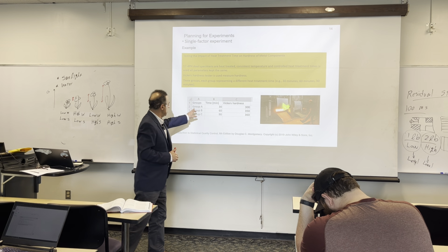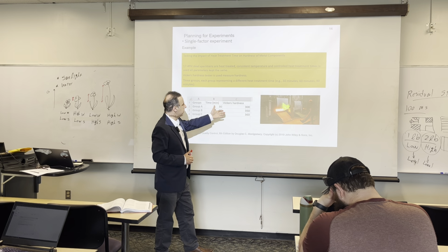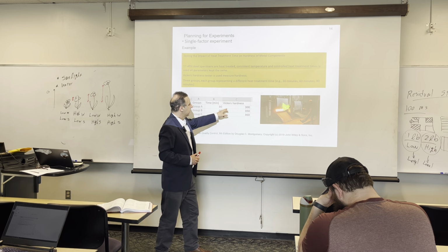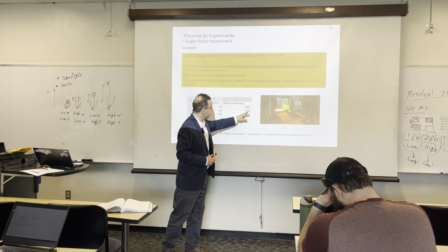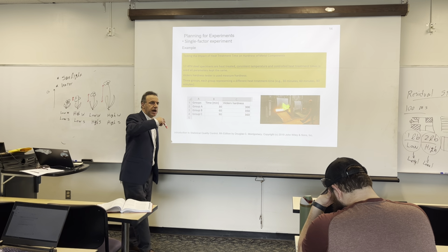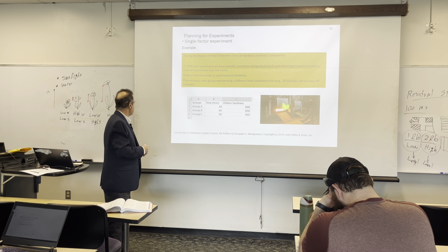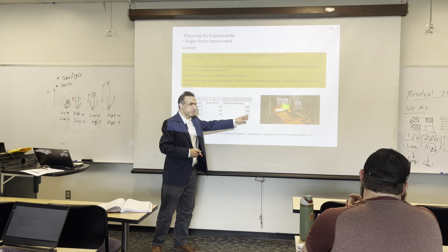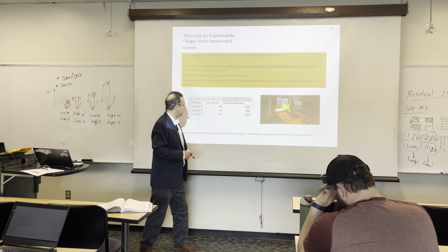Anyway, so they tested, and they see when they put the sample in the furnace for a certain amount of time at a certain temperature, the hardness was 300. And then at 60 minutes, 350, and at 90, maybe 360, 370, approaching asymptotically to one level.